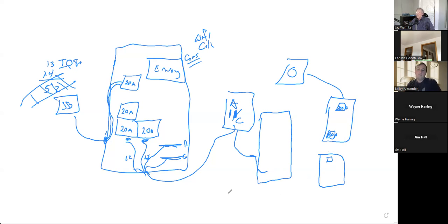And then I need some batteries. So this is going to be my battery system. And it connects in here. And I could also connect in a generator if I wanted to. And it connects in here. So this is the brains of the operation now. And from here, it connects in to the critical load panel. And it also connects in to my main load panel. All right. So does everybody see here all the different connection points?